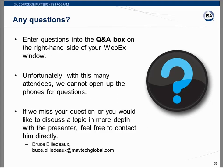Okay. What other software tools do you use in ICS systems for cybersecurity? One of the best ones, Wireshark, is probably the most common that we like to use. You can put that on there and record traffic for a long time. It's passive. You can apply it directly on any one of the systems or on a switch. So that's probably one of the biggest tools that we use to identify traffic.